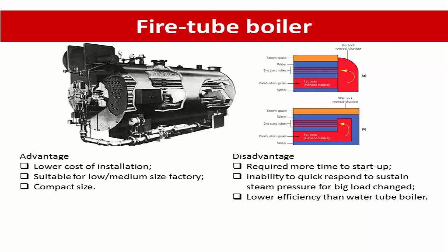Fire-tube boilers are basically suitable for clean fuels such as oil and gas, since dusty fuel causes fouling and erosion as it travels in the tubes. Capacity is limited to only 35 tons per hour due to the size of the shell. The pressure is not over 21 bar G or 300 psig. Only a small superheater, allowing about 50 degrees Celsius above saturation, is possible, as it is a problem to accommodate a large amount of superheater surface.